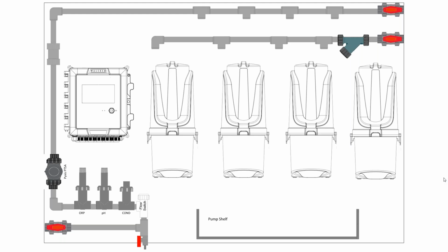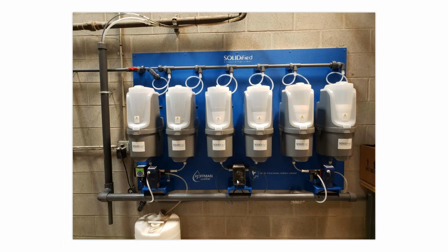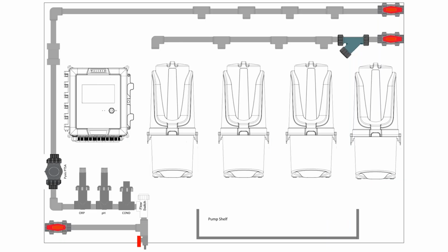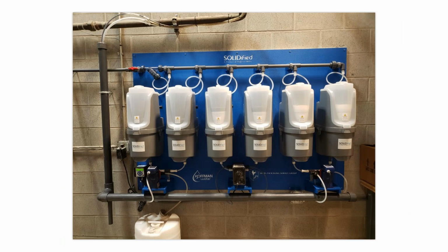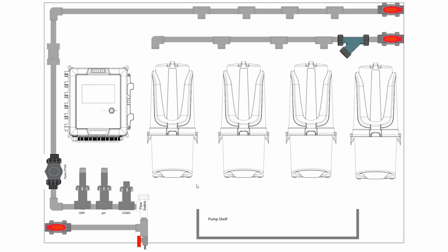So it's best practice to direct any of the overflow to maybe a common discharge pipe to go to a local floor drain. Otherwise, if the local environment's conducive for that, it would just overflow water because at that point you'd be low. So on these drawings here you could integrate an overflow on that.